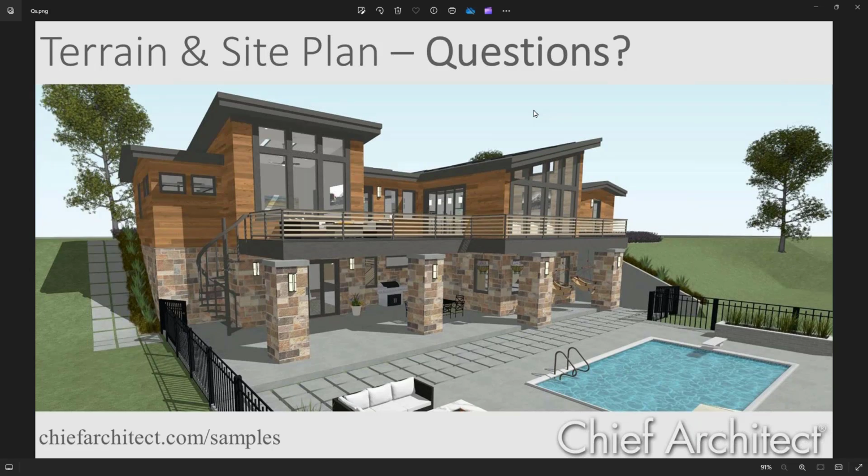My question is somewhat twofold, and I do appreciate these webinars. When I watched the video, I got the impression that you should use the elevation line in conjunction with the regions. From your video, I'm getting the impression that just maybe using one would be the best, because, and I'm going to go ahead and ask my second part too. When I've done that, and when I've gotten them close together, I go into my 3D view and it creates multiple spikes. What am I doing wrong?